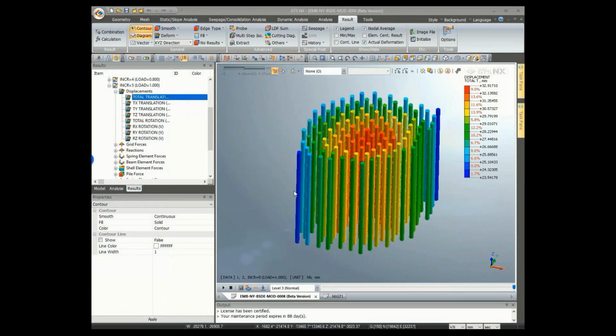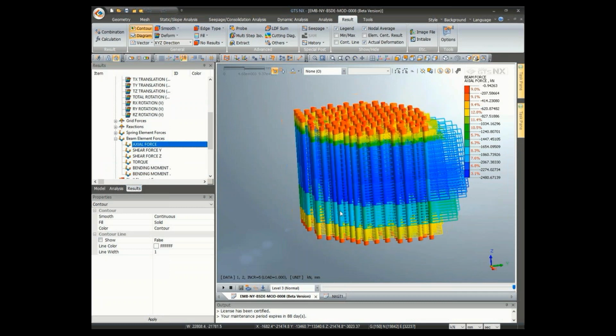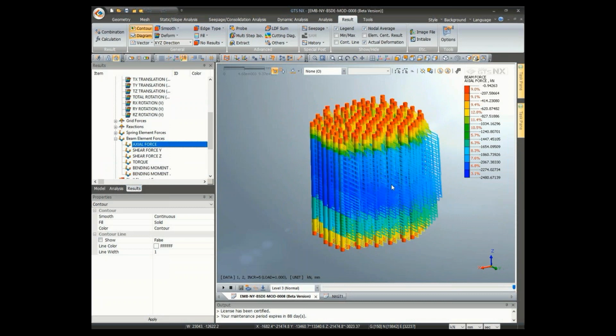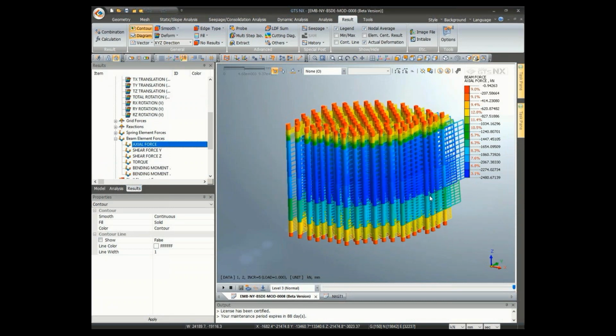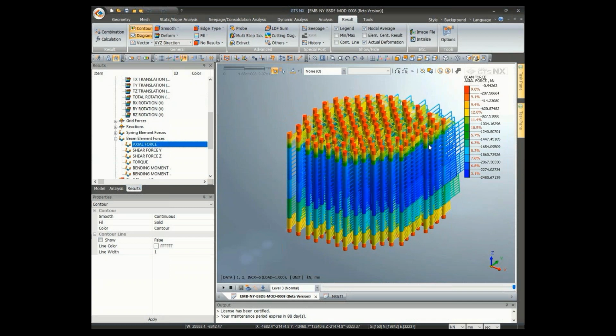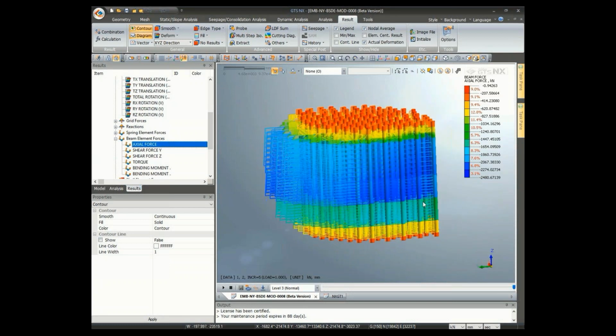So taking a look at the result of axial force in piles, as with the raft I have said before about extracting those values, we can extract the value of each pile. These values can be pasted into Microsoft Excel, so we can calculate the spring and easily send it to the structural engineer.